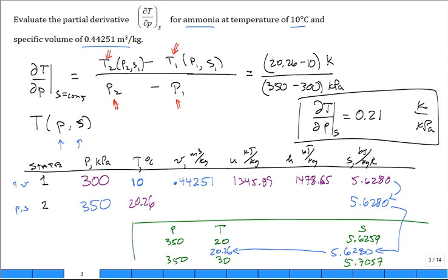That's right, and that's the closest pressure we got. Now you could go 250 or 350 on the pressure, either one. But since I like to do a forward difference, what we're doing is forward difference for the first derivative approximation. The other one would be backward difference in pressure. And the best would be central difference, but you need an even split above and below. And it would be double the work, but you'd get a better answer.